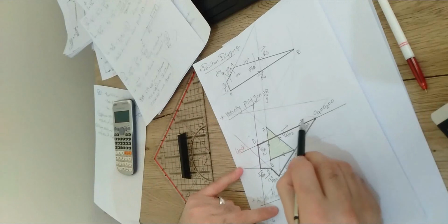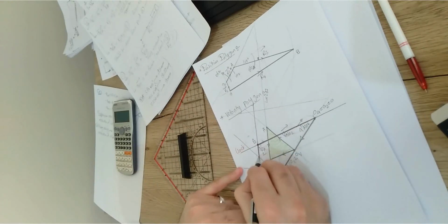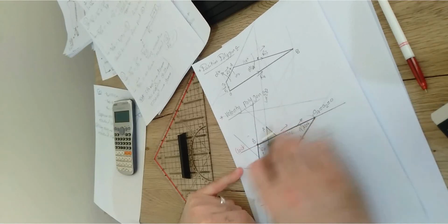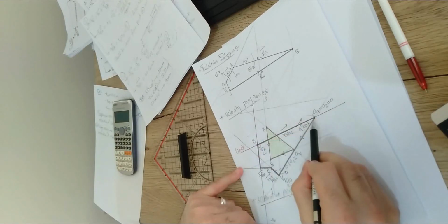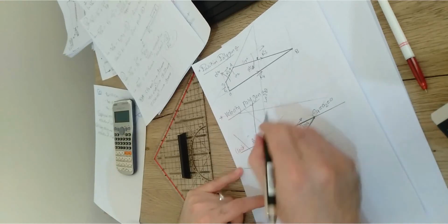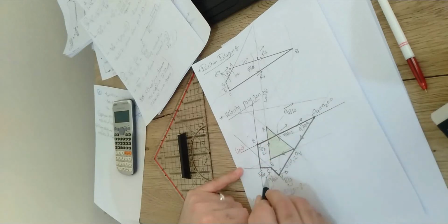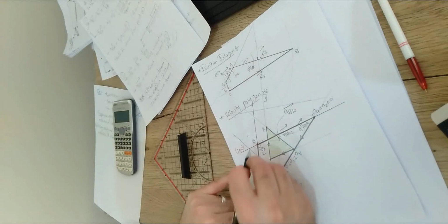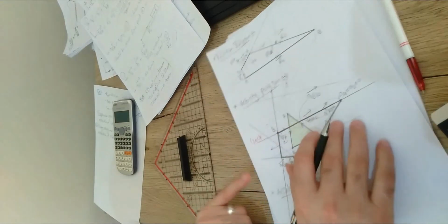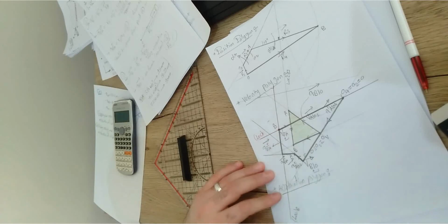So this new line here, and this new line, this should be the tangential component that we didn't find its value in the beginning, and this should be the sliding acceleration, right? Because it is set up between B and O, so this component, this line, should be the acceleration of B relative to O vector, and this line, we're already moving from A to B or B to A through normal and tangential. It means that this should be the tangential component. This should be AB relative to A tangential vector.